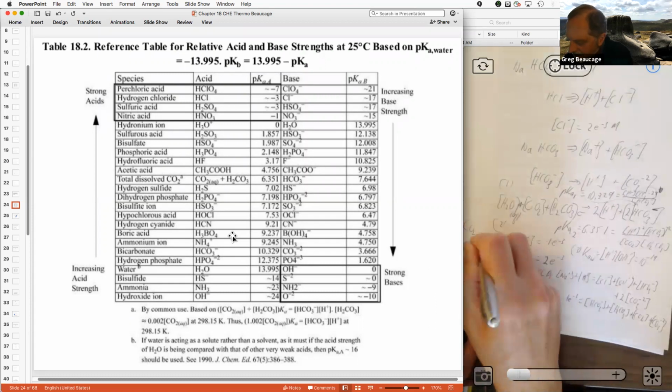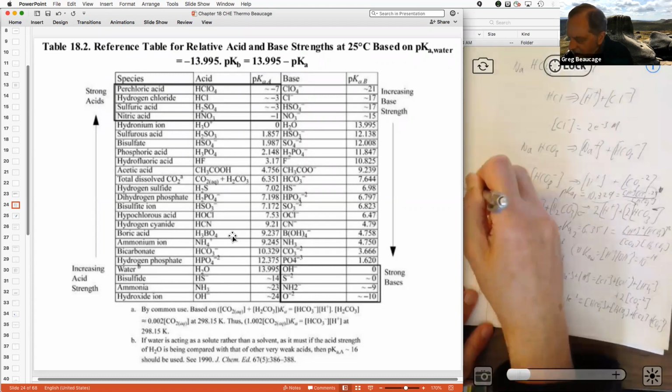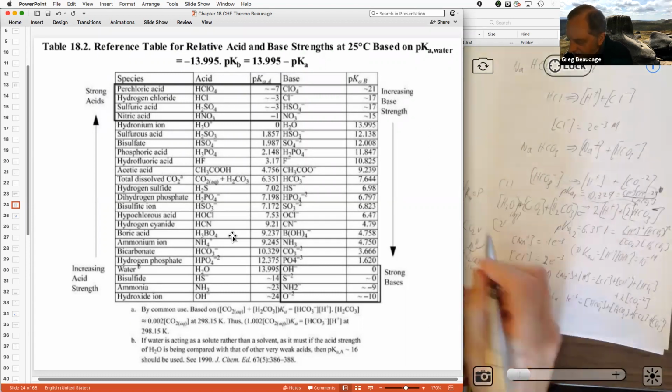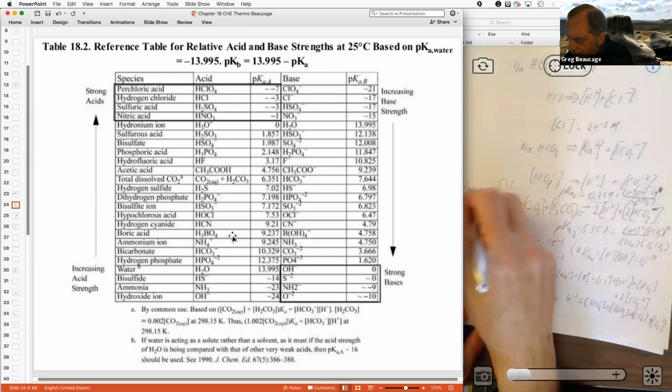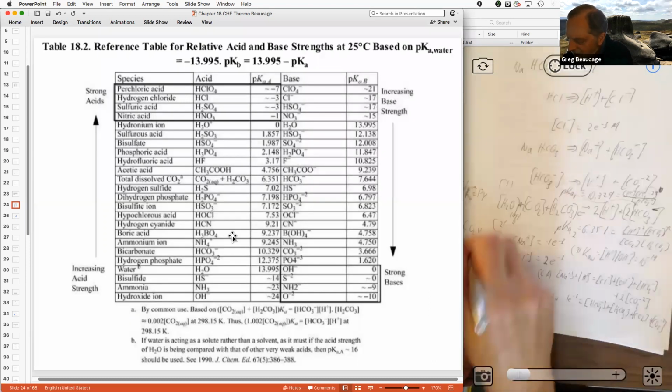So vapor and liquid. You're going to have a Henry's law constant that gives you the partial pressure of CO2 over this. Basically, Henry's law constant will give you the partial pressure, which is the pressure times the y composition of CO2 in the air.